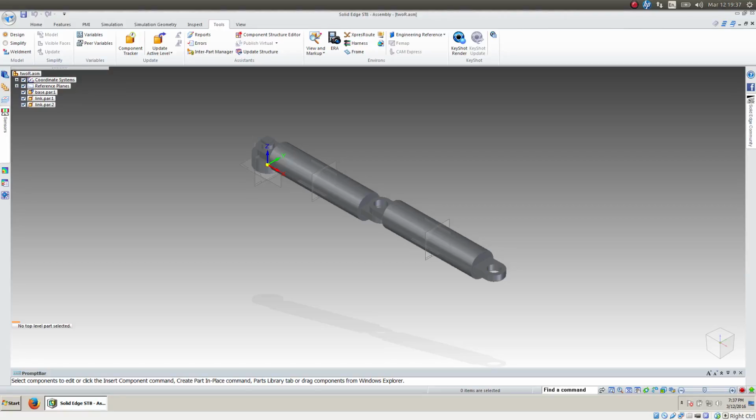In Dynamic Designer Motion, it's possible to export simulation data into a comma-separated value file, or a CSV file. It's also possible to import this data for your motion, and DDM will create a spline for interpolating between the data points for the simulation. And we're going to look at both of those now.